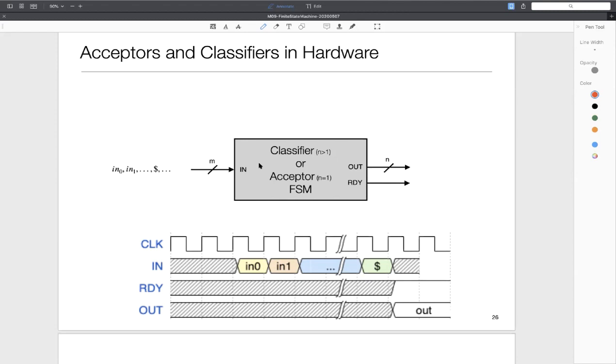So if the packet matches a particular string, I'm going to send it to one router, and if it matches some other string, I'm going to send it to some other router. They basically do a lot of bit pattern matching, and that is usually implemented by hardware implementing these kinds of state machines, which are classifying things into categories. Since the data rates are very high, usually this kind of stuff cannot be done with software. So there are finite state machines directly implemented in hardware, in chips, that do this kind of stuff.